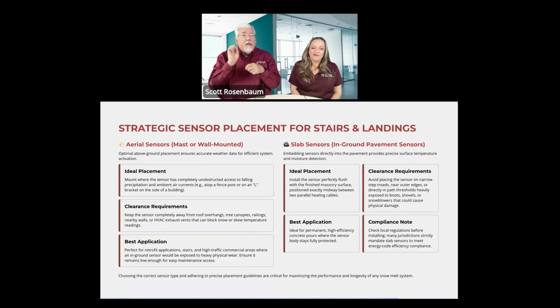And the only maintenance that you need to do on an electric snow melting system is to clean the top of the sensor. So that sensor has to be somewhere where you can get at it, but a vandal can't just go, hey, this is cool, and throw it away, or break it or whatever. So it's got to be where the snow always hits it.